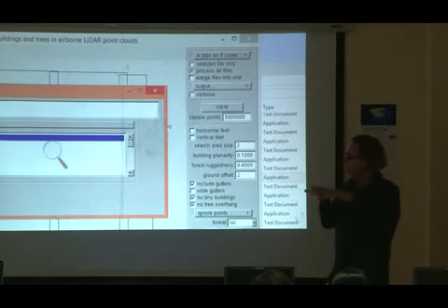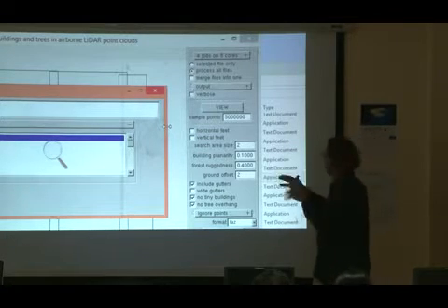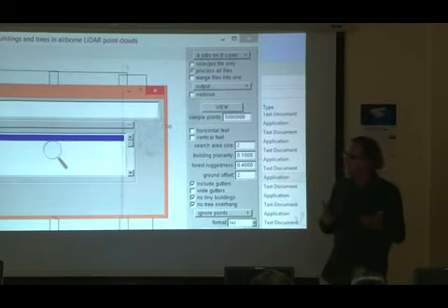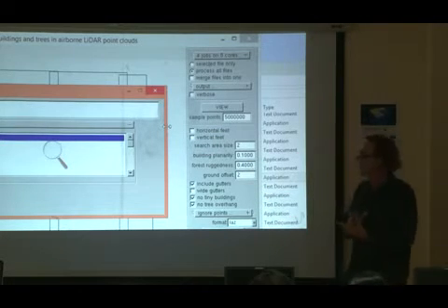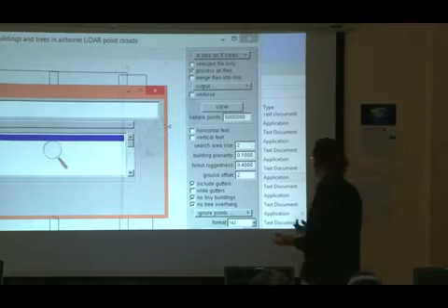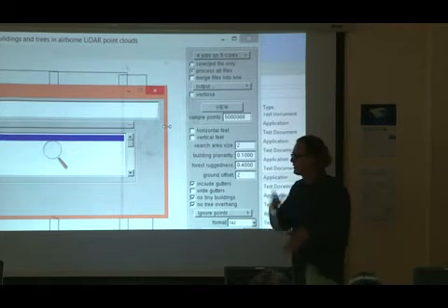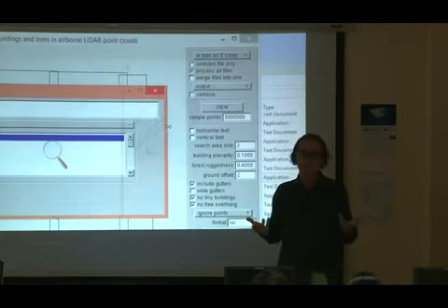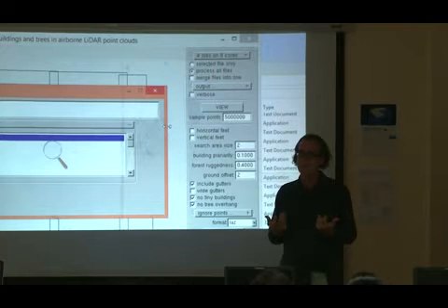Are they very planar? Is the standard deviation just about 50 centimeters? Then it's most likely a plane, and planes are most likely roofs. Then it's a roof. Is it very non-planar? Is the standard deviation high? Then it's most likely something fluffy. Now that could be